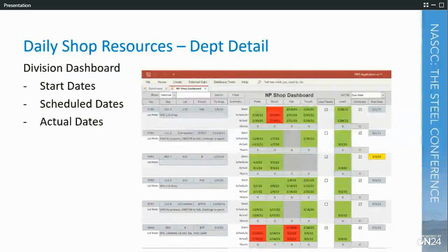In the past, we would just put stuff in the shop based on delivery date. And like Derek mentioned, sometimes you have a bunch of lots and releases that have the same delivery date or are within a week, but they're all different. This one has high man hours, this has low man hours. And if you go strictly off the delivery date, you're pushing the work out, which means you could be over processing, stacking material up, adding more material handling, or you have another department that's still waiting for material to get there to work.